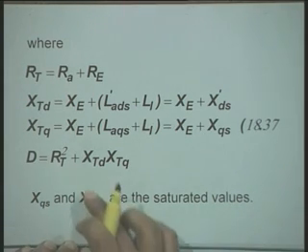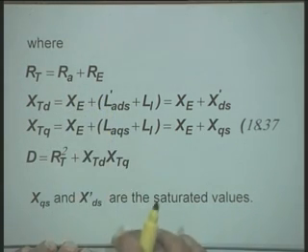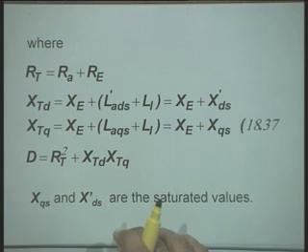And further, when you write these terms in our per unit system, the line inductance or synchronous machine inductances are equal to the synchronous machine reactances and line reactance. Okay. Therefore, we do not make any difference between the inductance and reactance, because in per unit system our omega 0 is 1. Okay.